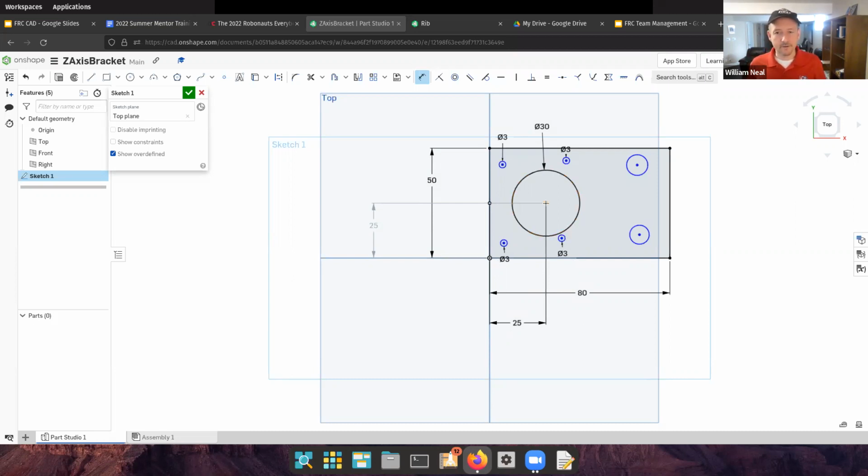And in fact, from this point here, it should be 11.5 millimeters left and up, or sideways and up or down. So we'll try to do those constraints now. So one way I can do that is to take these 2 points here, holding down shift between them, and I believe that should be 11.